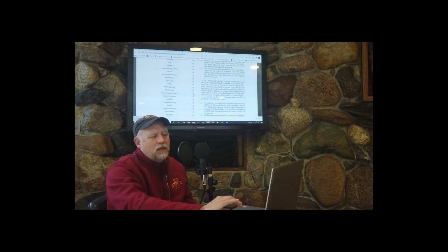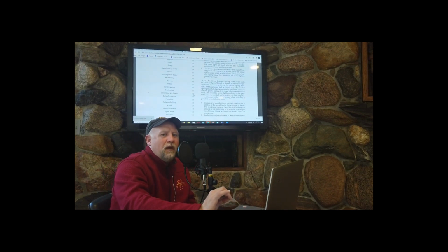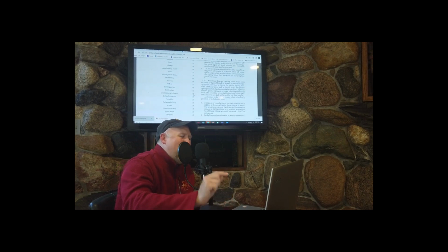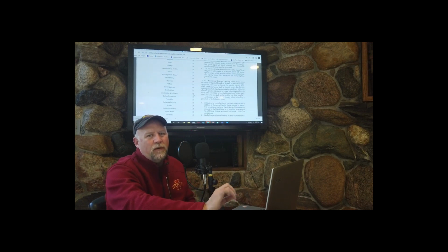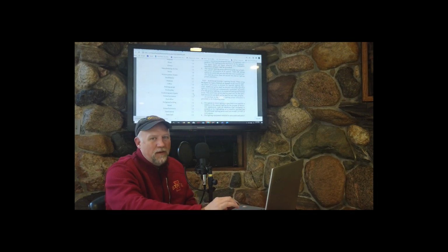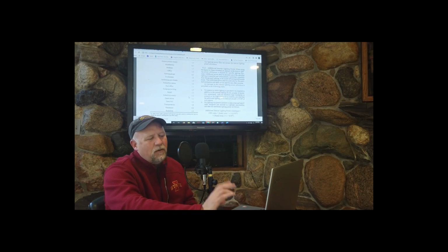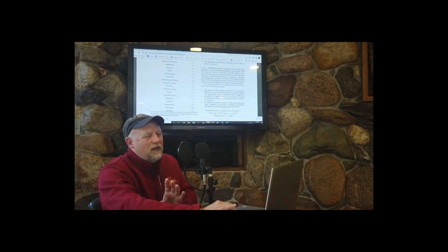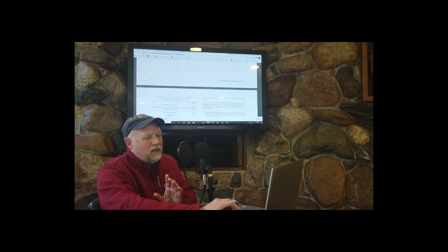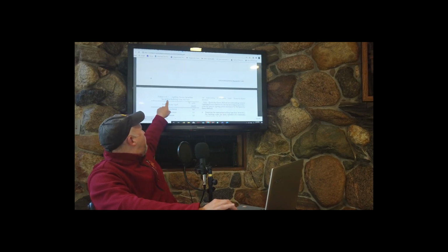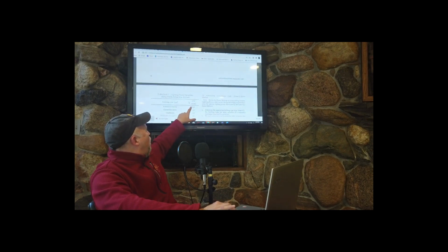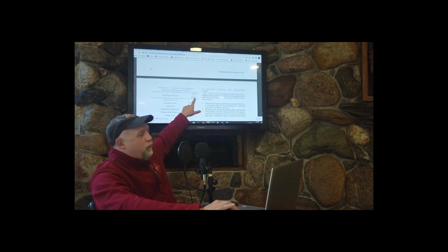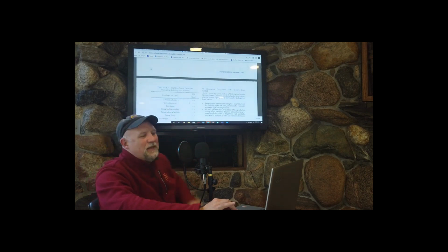But something important to know, though, is that modern light fixtures, LED light fixtures, are capable of getting down to half of these levels, like around half a watt a square foot, 0.6 watts per square foot. They are much, much, much better than they ever used to be. So I just want you to know that it's governed and that this is the average here. This is the building area method. If you took the whole building area and you divide out the watts of electricity used on lighting per square foot of area, that's what this limitation shows us.